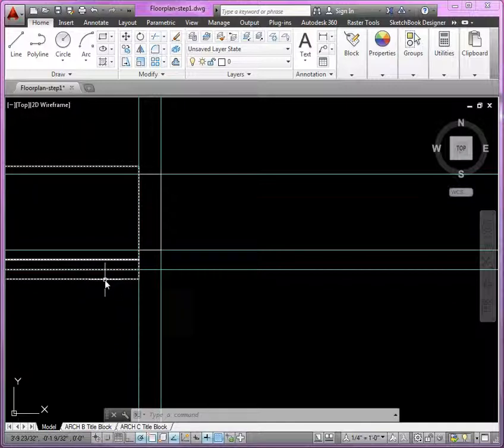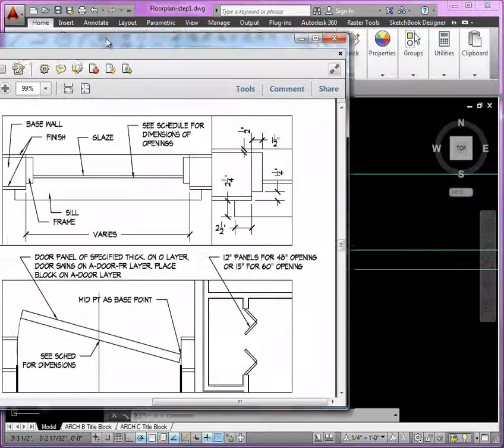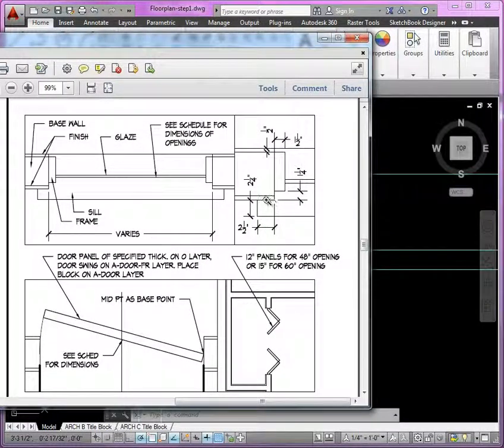And then from the face of the exterior finish there should be 2 1/4 inches. And I realize that in our diagram here, you can see I don't have the other layer of finish wall there. So just go ahead and work with the offset and what you have as your finish wall.